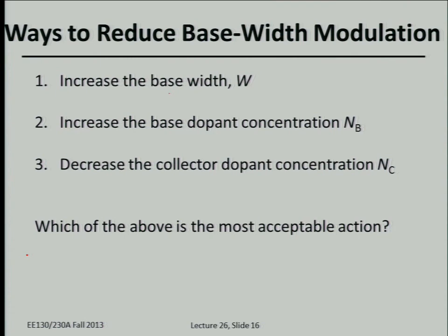Which one of these is most affected when you increase the base width? The transport factor, right. So the transport factor goes down, which means that gain goes down.